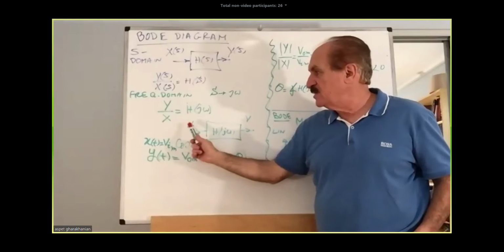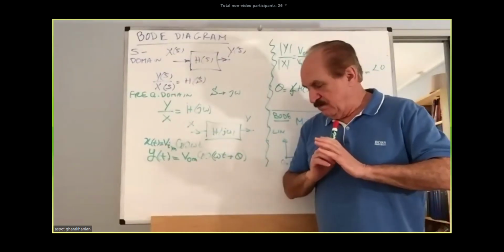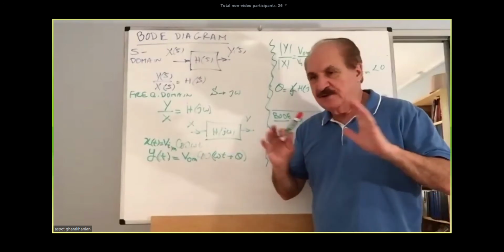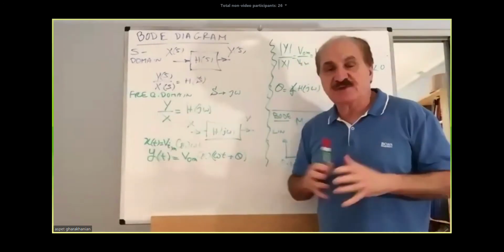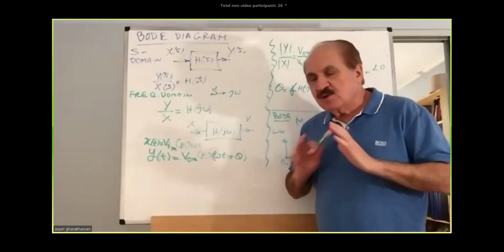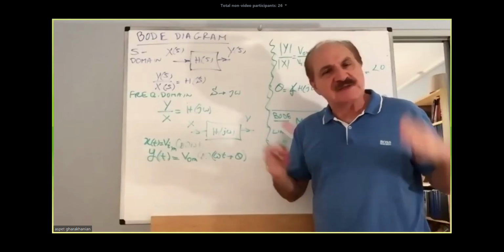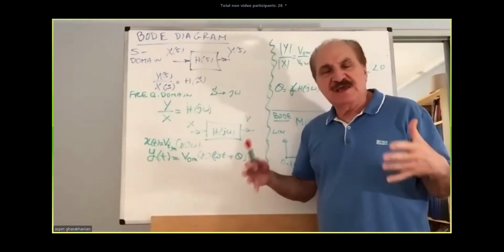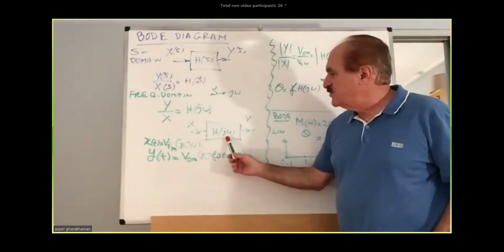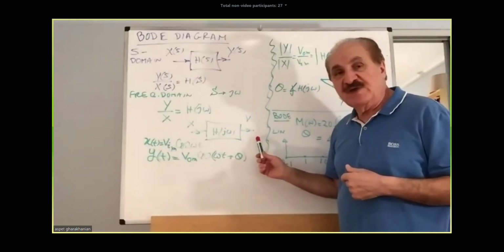Here, x is no more a step or ramp or any other kind of general waveform. It is only a cosinusoidal waveform. So x becomes a phasor, exactly the same way we did in AC analysis. H(j omega) is the operator that converts that phasor into an output phasor.